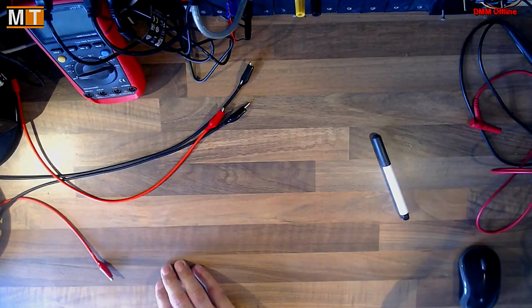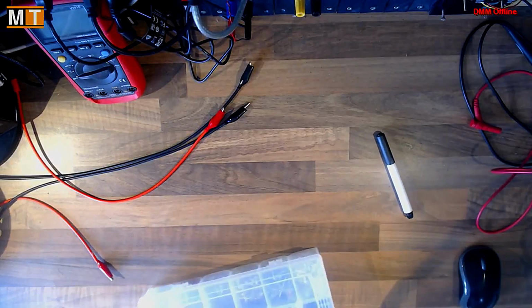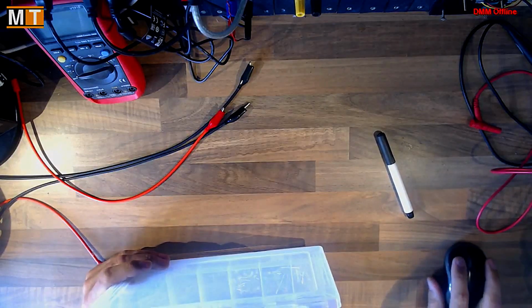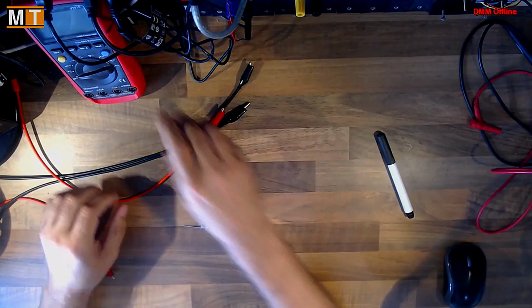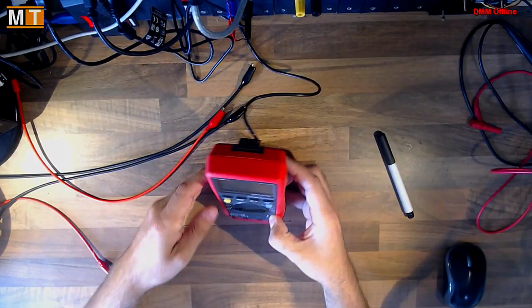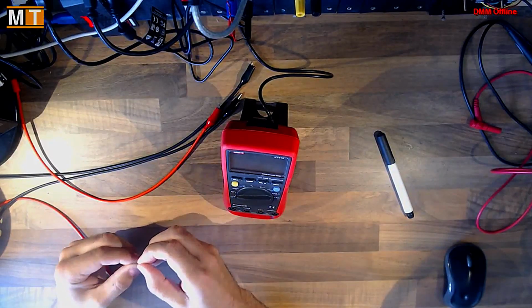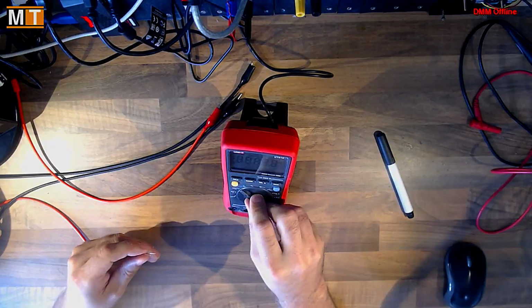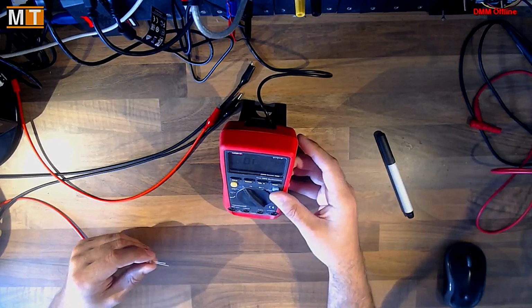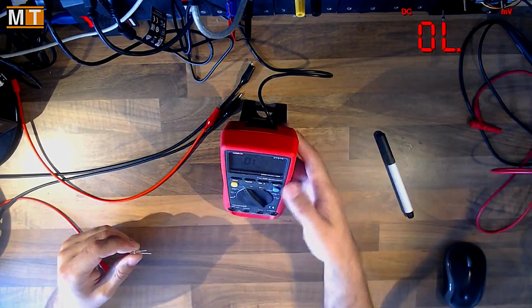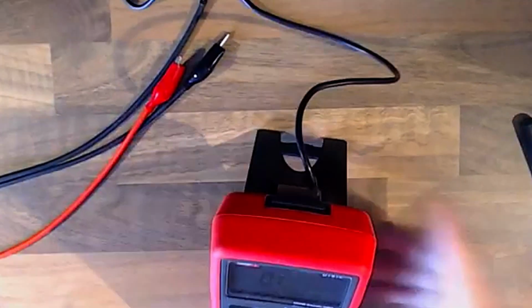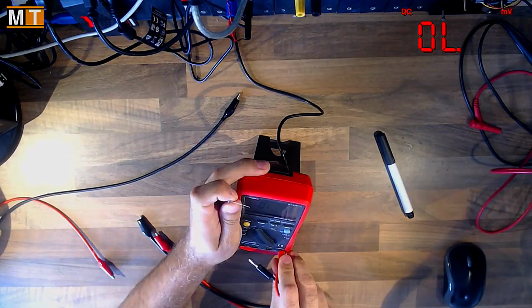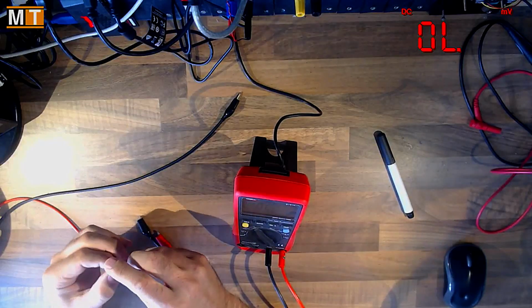Okay, let's get an LED from my box. I choose red. A nice 5mm red LED. Finding the forward voltage of an LED can be done straight off with a decent multimeter. They usually have a diode range. If I bring this up to the camera so you can see, we've got a little diode symbol on there. That should allow me to measure the forward voltage of the LED.